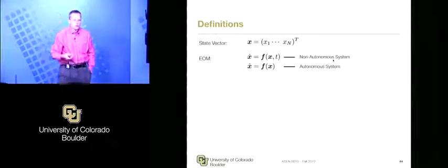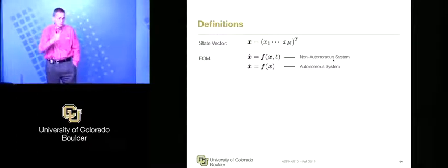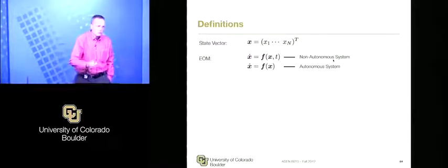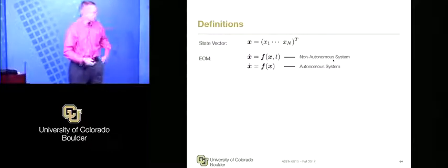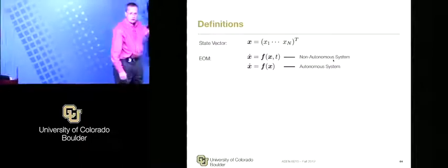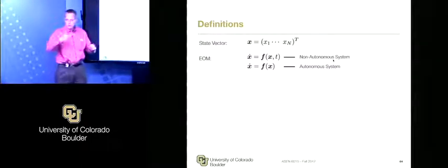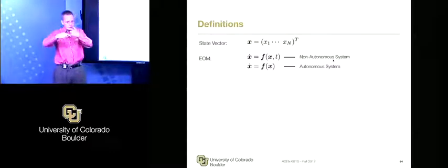What do we do if we have 7 instead of, because you said we could substitute MRPs with quaternions. There must be a closing relation somewhere. Right. So you have to enforce a constraint. Now you can integrate these, and your equations of motion, if you give it an omega, will tell you how your quaternion rates evolve and how you can integrate them.